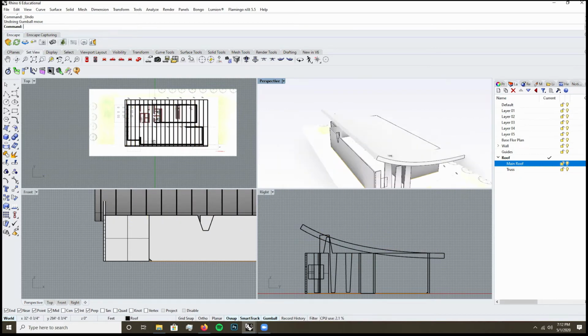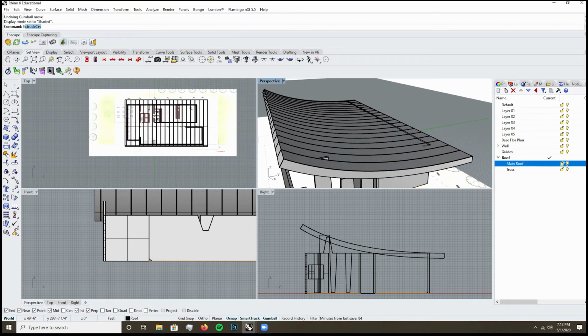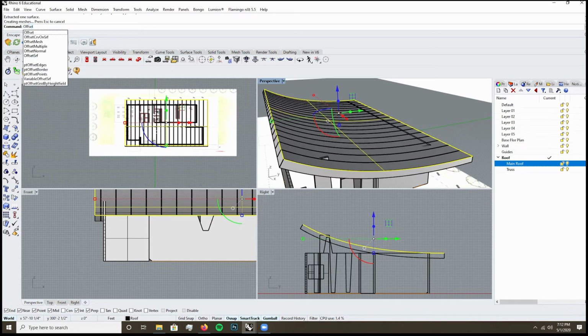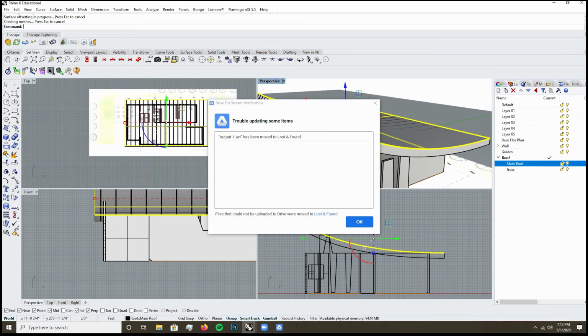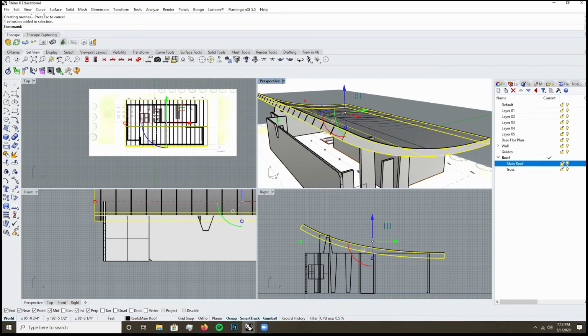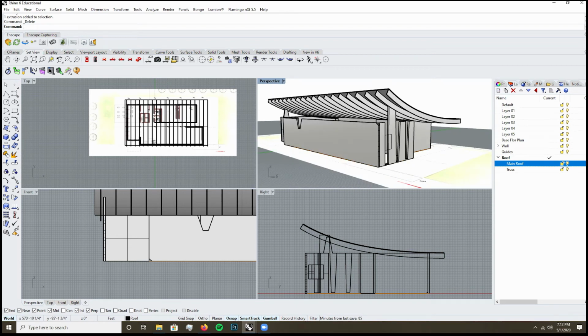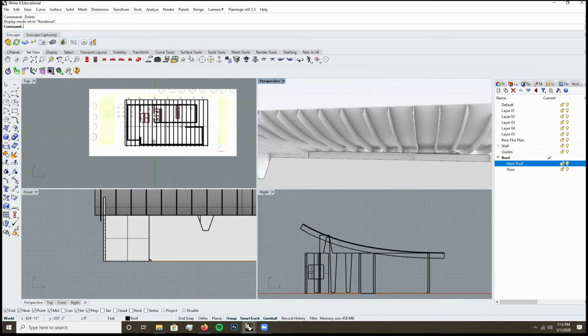You can always come back to, let's say you just made that roof to generate the trusses, you could come back here and press extract surface. I'm going to copy that top surface, and then I'm actually going to hit offset surface and, let's make a 4-inch roof here, and then for right now you can hit this and turn that off. And that's another way you could get a bunch of, let's see how that is looking, and that's how you can get a series of trusses.